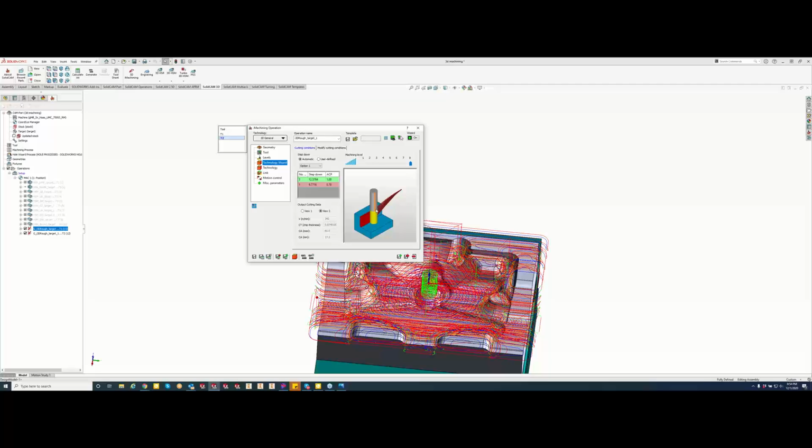Mm-hmm. I've been in shops where guys are cutting electrodes for EDM machines, and they need a very fine resolution. So these guys are using 20 thousandths diameter end mills, and you do not want to put any kind of stress on that diameter of an end mill. Just looking at it, you're afraid you're going to break it. And with iMachining, we're able to make those cuts and have the tool last. So yeah, it's applicable across all applications.